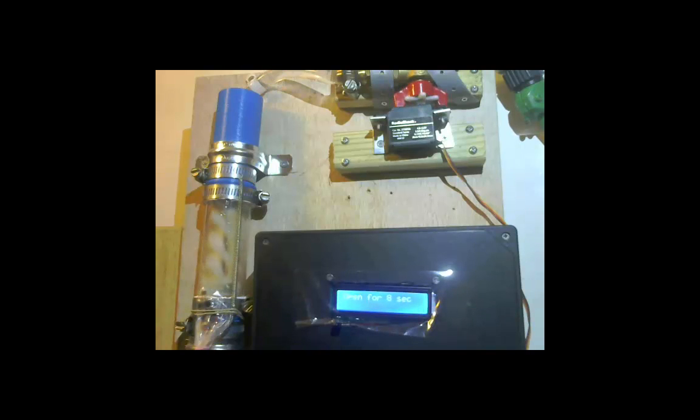Pressing the number 8 opens the valve again. There is a 2-second delay before the Hall effect sensor is allowed to record data. Once the 8 seconds have elapsed, the flow data is displayed and the valve closes. Finally, there is a 3-second pause before additional IR remote functions can be performed.